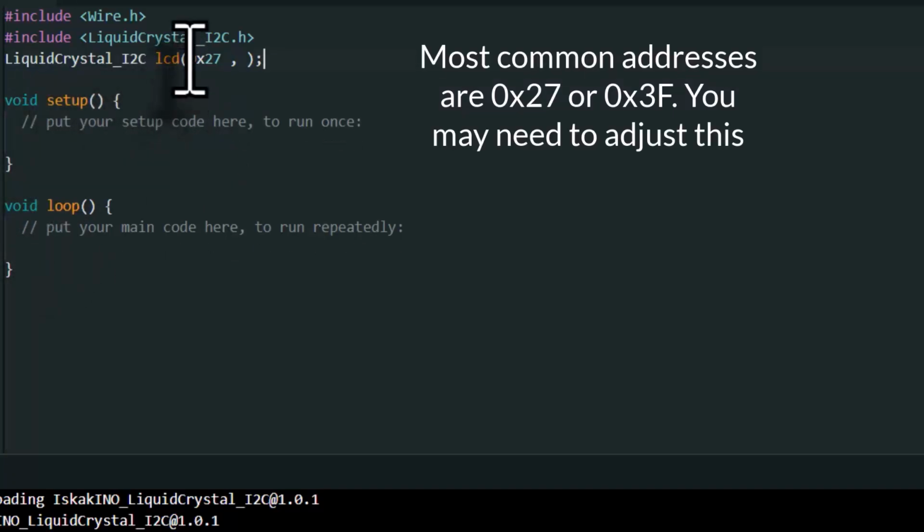For our LCD today, let's first use 0x27. If we see any error or the LCD doesn't work, we can come back and change it to 0x3f.